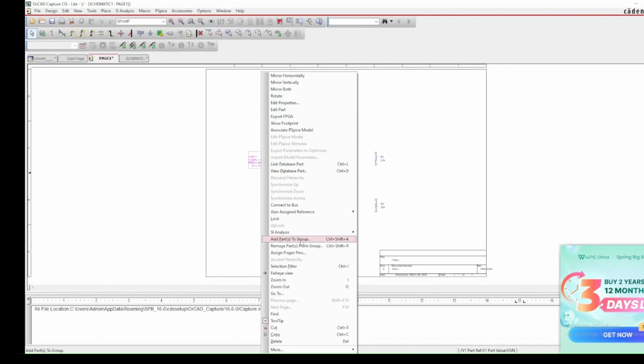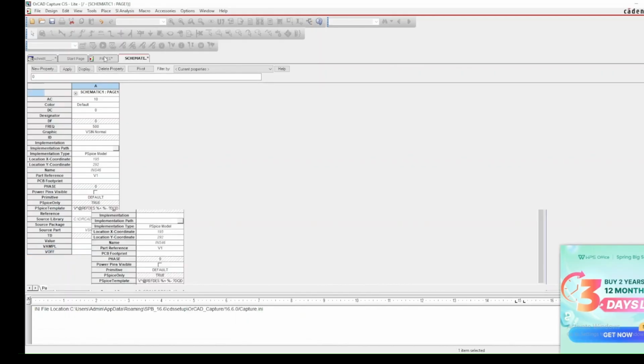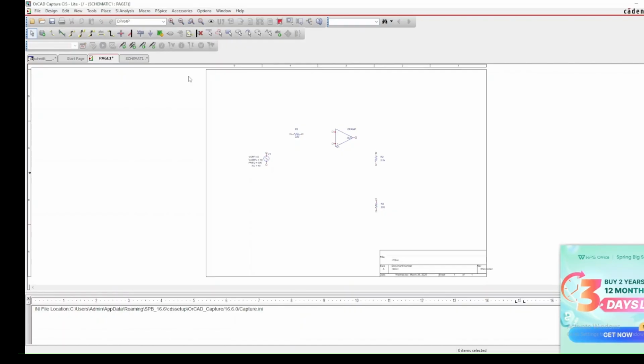So we can apply it for input and output. And then let's see the properties here, and you can see every value has been given here. And let's also give it V off, and then let's connect all these components with wire. You can click the component and press W on your keyboard, and you can connect all these parts.